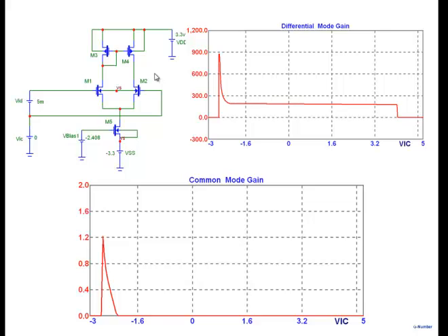All right. This is what the simulation results illustrate: what happens as I change the common mode voltage here. So note, I have a normal differential pair here. And to this differential pair, we have connected a 5 millivolt differential signal. Note that this 5 millivolt comes across this one here. So 5 millivolt is the differential signal, and the common mode voltage is here. This is common. VIC, as you can see here, goes here as well as goes here. So that's the common mode signal here. And 5 millivolt is the differential signal here.